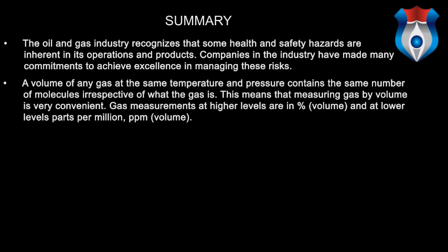A volume of any gas at the same temperature and pressure contains the same number of molecules irrespective of what the gas is. This means that measuring gas by volume is very convenient. Gas measurements at higher levels are in percent volume and at lower levels in parts per million, ppm, volume.